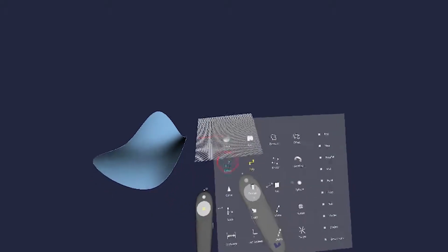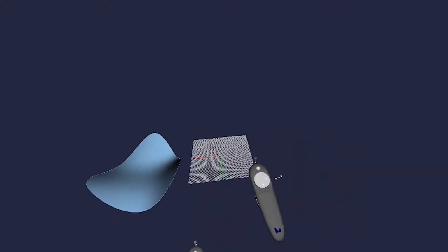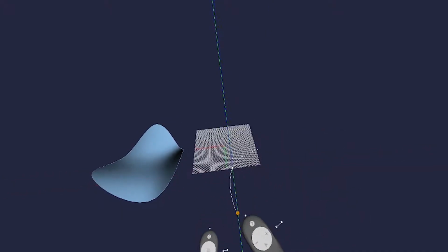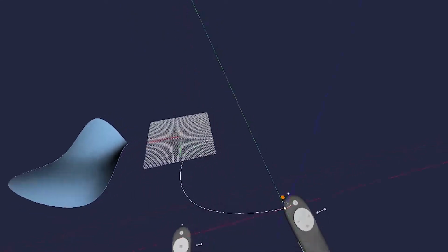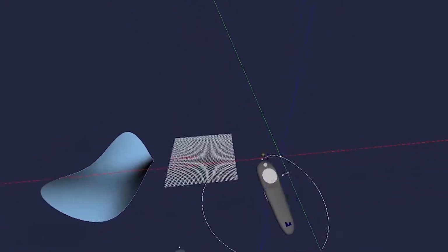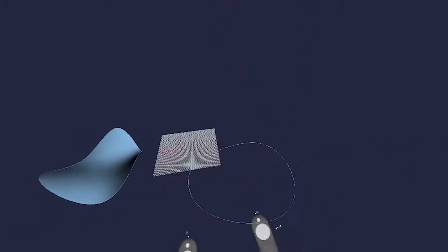The next tool is loft. So using the same spline tool as before, go ahead and draw a closed loop that is flat on the XY plane. The magnetic handles will allow you to make sure it's planar. Once you have that closed loop, check underneath to make sure it's flat.